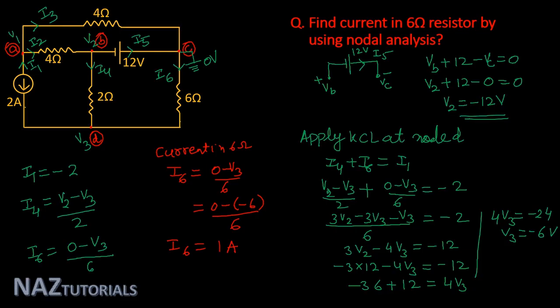This is our answer. So here you see the circuit solution becomes simpler if you select this node as a reference node. If you select node D or node A as a reference node, then the solution will become lengthier, and when you solve all the equations, you will get the answer. So this is the concept for assuming reference voltage in a particular circuit.